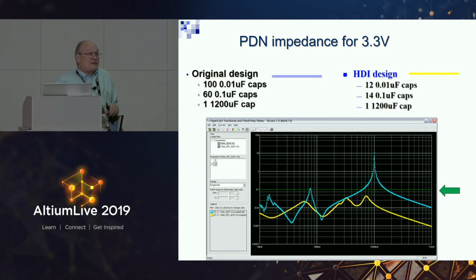We also found that the decoupling caps don't have to be near critical devices. They just have to be in a matrix. So you put them in non-critical areas in a matrix. You don't have to put them next to critical devices.